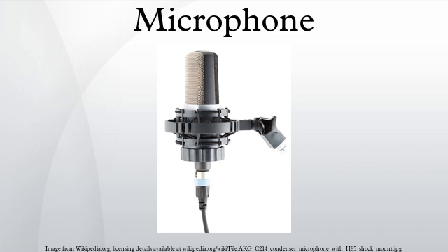Impedance matching. Microphones have an electrical characteristic called impedance, measured in ohms (Ω), that depends on the design. Typically, the rated impedance is stated. Low impedance is considered under 600 Ω. Medium impedance is considered between 600 Ω and 10 kΩ. High impedance is above 10 kΩ. Owing to their built-in amplifier, condenser microphones typically have an output impedance between 50 and 200 Ω.